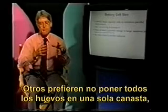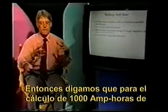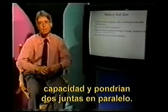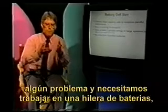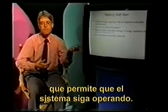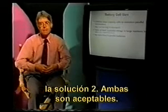Others say, well, I don't like putting all my eggs in one basket, so I would like to at least have two strings. So let's say in our case of calculating 1,000 amp hours of battery capacity, you'd choose batteries that have roughly 500 amp hours of capacity and put two of them together in parallel. Then you'd have two strings. The reason for that is if there's a failure or a problem and you need to work on one string of batteries, you can disconnect it and still have another string that allows your system to operate. I don't draw too strong of a distinction between the one solution or the two solution. Either one of those I think is acceptable.